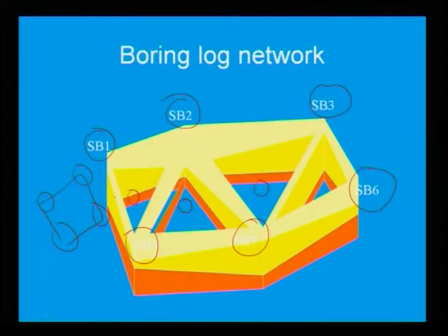There is no straightforward rule; this is a thumb rule. Initially you plan for 6. After seeing the boring log data of the 6, if you see the soil profile is varying from one borelog to another, then you may decide additional boreholes may be carried out at the center of the proposed plan. At the center, additional one, additional one, additional one.